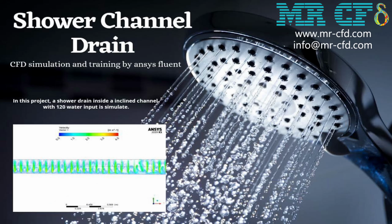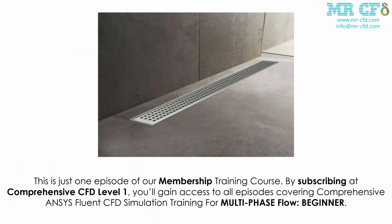In this project, a shower drain inside an inclined channel with 120 water inputs is simulated. The shower drain inside the inclined channel is simulated and analyzed by ANSYS Fluent software. In order to analyze the air and water flow inside the channel, a standard k-epsilon model with the use of standard wall functions is exploited. A multi-phase VOF model has been used to investigate the two-phase flow of air and water within this channel.